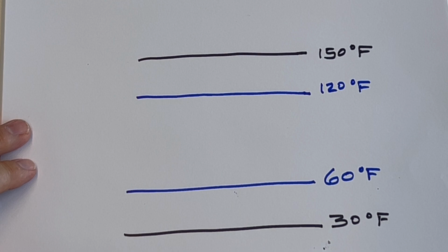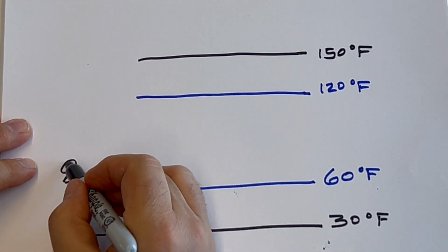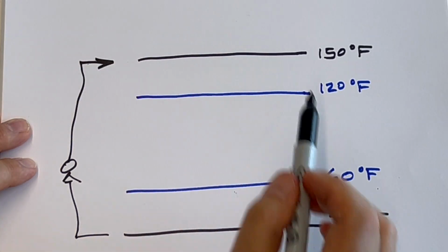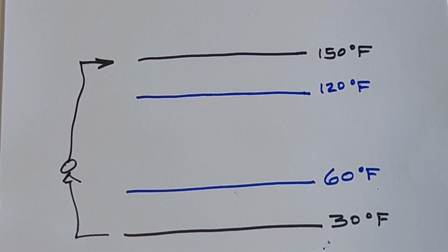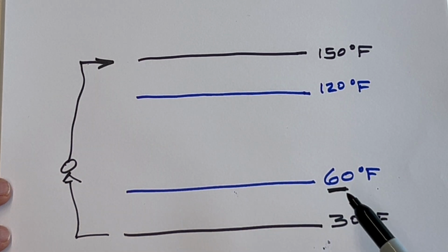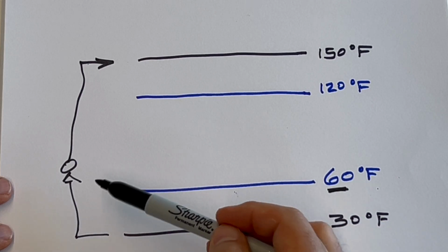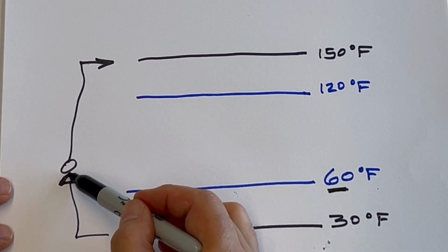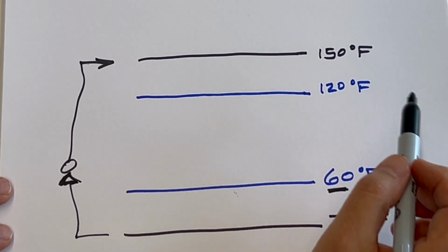Now the compressor is compressing from 30 up to 150. That's a pretty big lift. That will have a lower efficiency than a heat pump that is heating air with 30 degrees outside temperature. We do benefit from the relatively warm basement. That's a pretty good heat source, and we're pumping it up to 150. That's high. This is a little higher than the other one, but in the final analysis, this efficiency will be slightly lower than an air-to-air heat pump because of the high water temperature.